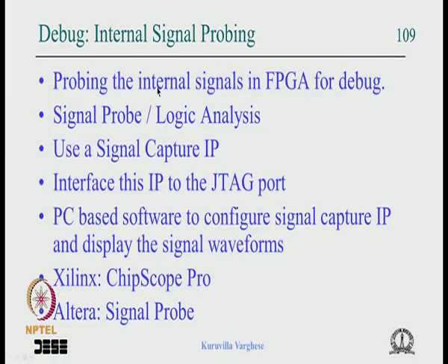So it's a great tool. Once you have some complex circuit going to the FPGA, to debug it, these logic analyzers can be used, and Xilinx calls it ChipScope Pro and Altera calls it SignalTap, and it's very easy now. Over the years it has become a very nice tool.